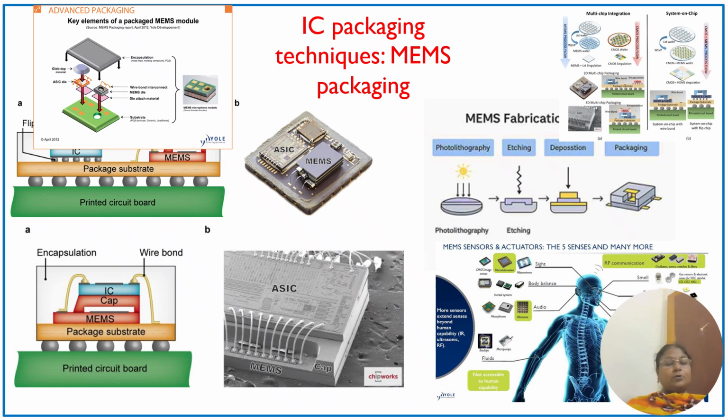And on top you have this MEMS unit, then you have this IC. Now a wire bonding technique is suitable here, from the substrate towards your IC. So you can see the connectivity. Why you need this connectivity? So this connectivity is going to carry the electrical signal as input, and it's going to fetch your output. So that is the wire bonding feature.